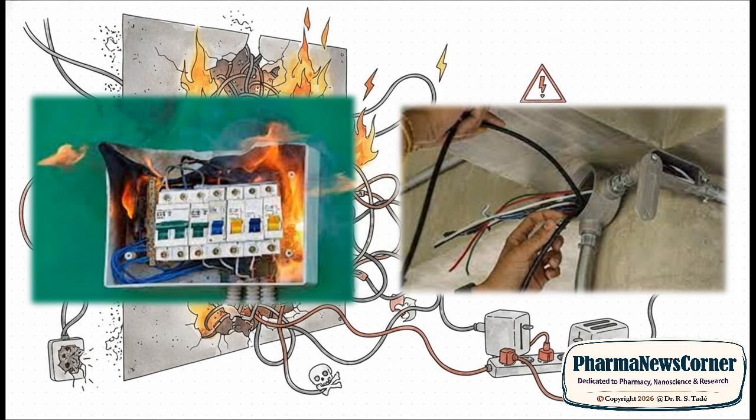And speaking of electrical hazards, this one is incredibly relevant to all of us as students. Did you know that over 60% of fires are actually of electrical origin? They happen because of super common things: faulty wiring, overloaded breaker boxes, daisy-chained extension cords. The precautions are simple but absolutely critical. Use certified appliances, replace broken plugs, and never ever overload a single socket. These are the exact kinds of hazards that are just lurking right behind the drywall of any older campus building.